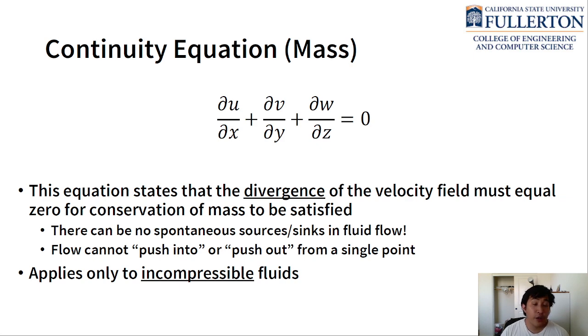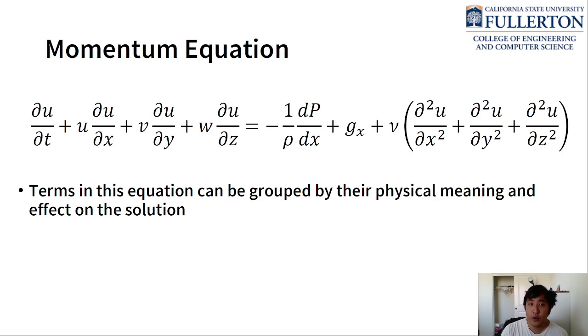But I do want to note that the form of the equation that I have here only applies to incompressible fluids, okay? If you have a compressible fluid where the density is a function of pressure, or it can change, then the continuity equation takes a different form. But that's usually a bit beyond the scope of an introductory fluids class. But I did want to make that note here.